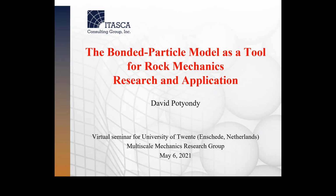And one thing about the bond models used in the solid mechanics community is that the most useful model, the parallel bond model, can transfer moments. And I'm not aware of a cohesion model of ours that would also be capable of transferring moments.